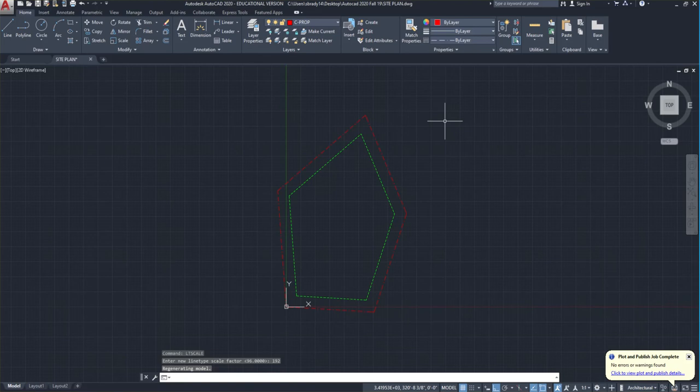I always would question this: I'm not scaling a scale that has already been scaled, right, and making it off. Every time I type in a new LT scale, it creates that setting according to a zero point, right? It's fresh every time. So that looks a little bit more appropriate.